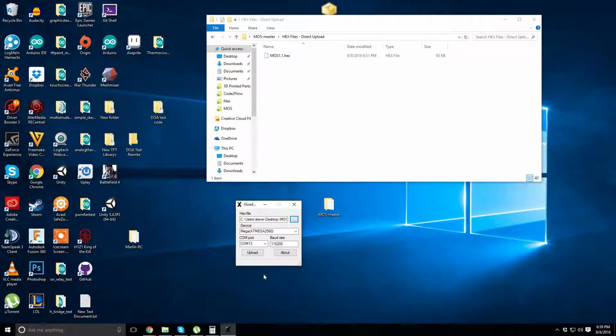And now that everything's installed, when you plug it in, you should still see your standard operating screen. Also, when you're uploading your software, do not have your unit turned on. Keep your unit off. Do not plug it into the wall. Just use your USB, which is enough to power the unit and to program the unit. So do not have it plugged in to the 120 volt or 220 volt coming out of your wall.